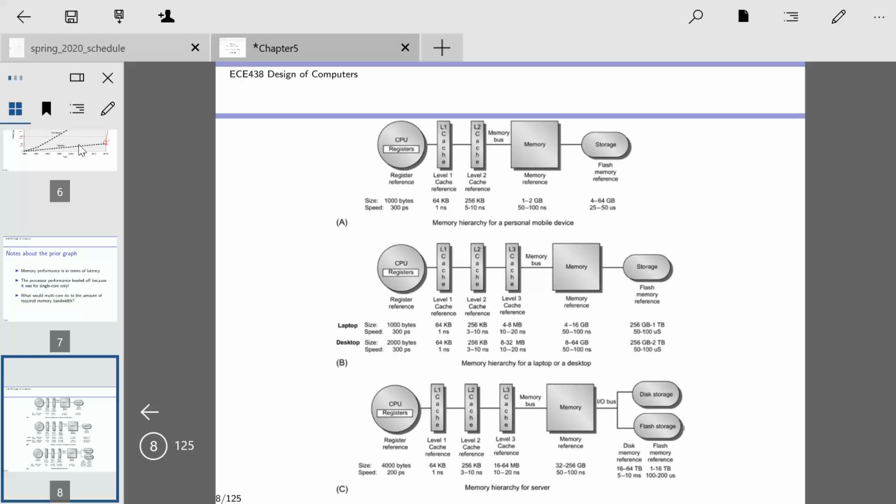Now, as we saw with the R4000, more aggressive instruction level parallelism techniques will actually split up the access to the level 1 into multiple stages. For our simple 5-stage pipeline, there's single cycle access to the level 1. These memories that we talked about in our single cycle processor, when we say, oh, well, we have a separate instruction and separate data memory, well, those are now caches. Those are our level 1 caches, and that's a split cache configuration. And we're going to talk a little bit more about that here in a couple slides.